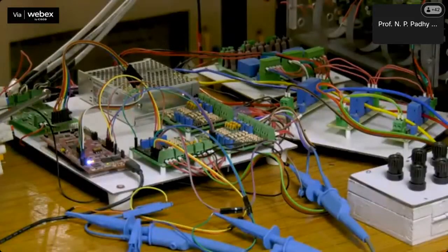For efficient triggering of IGBT switches, the generated PWM pulses from the DSP are shifted to 15 volt by using a level shifter. Now, the level shifted pulses are ready to be given to the Semikron stack. To avoid grounding issues, the electronic circuits, such as sensor circuits, biasing circuits and level shifter circuits, are powered by a common DC source with different voltage levels. Hardware demonstration of the grid integration.